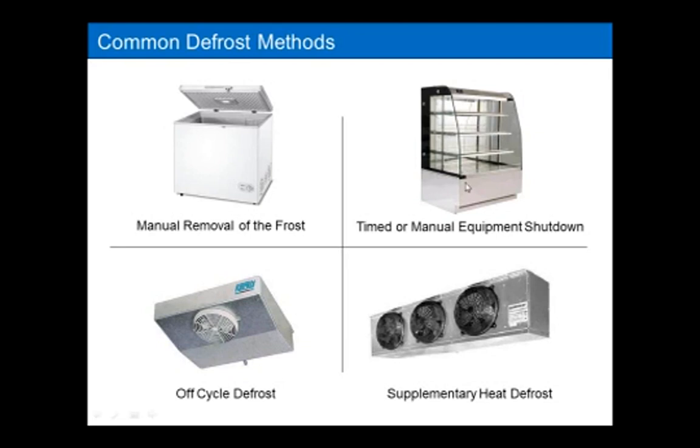Other systems use a timed defrost method where they just shut the unit down and let it naturally defrost every so often. They use a time clock or somehow to just shut the unit down, or somebody manually just shuts the unit off and lets it defrost overnight. So there are some systems out there where the manufactured or engineered defrost method is just shutting the unit down and emptying the product out of the case maybe, or just leaving the product in the case for a while and shutting it down for an hour or two. So that's another method out there, and again, we're not going to cover that method.